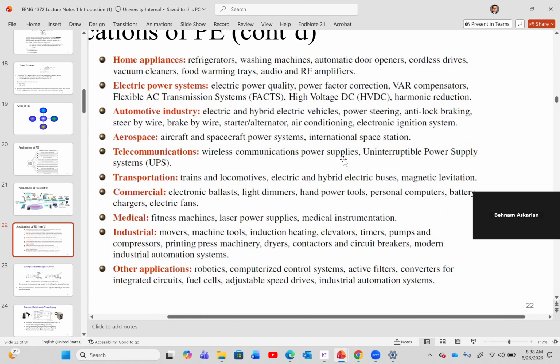This is one example. The other example was HVAC. In previous ones, because it was connected to the engine, when the engine rev went higher, the compressor was going faster, but you didn't need that much compressor. So then they had to add a clutch to the compressor. So these older cars, most of the HVAC has a clutch actually, because the compressor is connected to the engine with a pulley and with a belt.